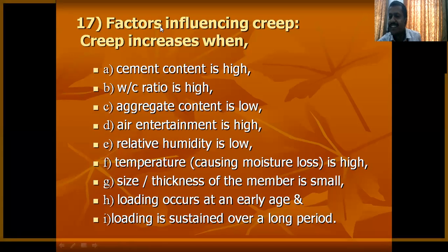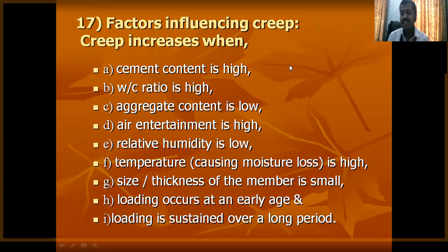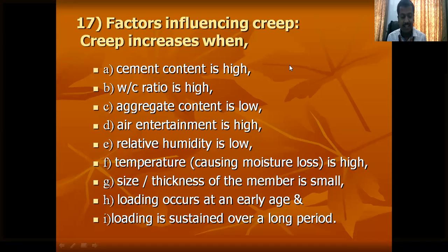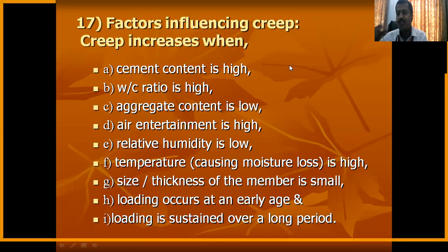What is grade of concrete? See, this word grade has its own meaning. Listen everyone carefully, grade is nothing but the characteristic strength of the material. In the case of concrete, grade is nothing but the characteristic strength. Now what is characteristic strength? You have studied the definition. Characteristic strength is defined as that strength below which not more than 5% of the test results are expected to fail. Correct, am I right? I think you have gone through this definition.